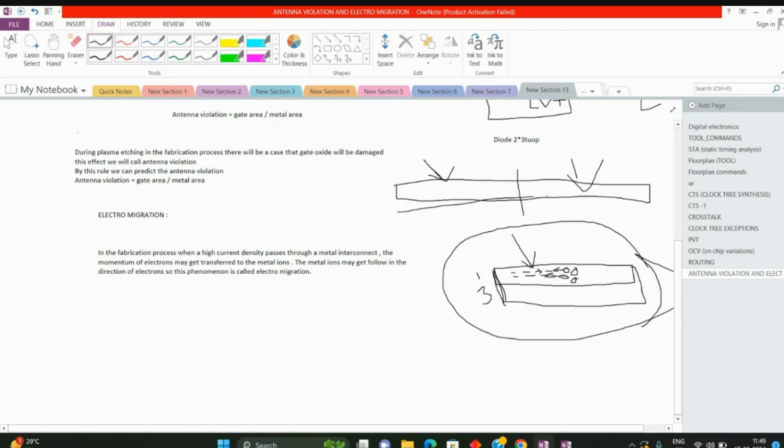Normally, any people, freshers or experienced people, if asked how you will fix crosstalk, will say shielding I will apply. But in reality, that is theory. For every case there will be one kind of textbook solution, but in reality it's not like that. Even for crosstalk we will check the net length, how much the net is causing delay, how much the cell is causing delay. If you make that cell cause very little delay, then it won't be affected by crosstalk. That's it, simple. Finish, your crosstalk is fixed.